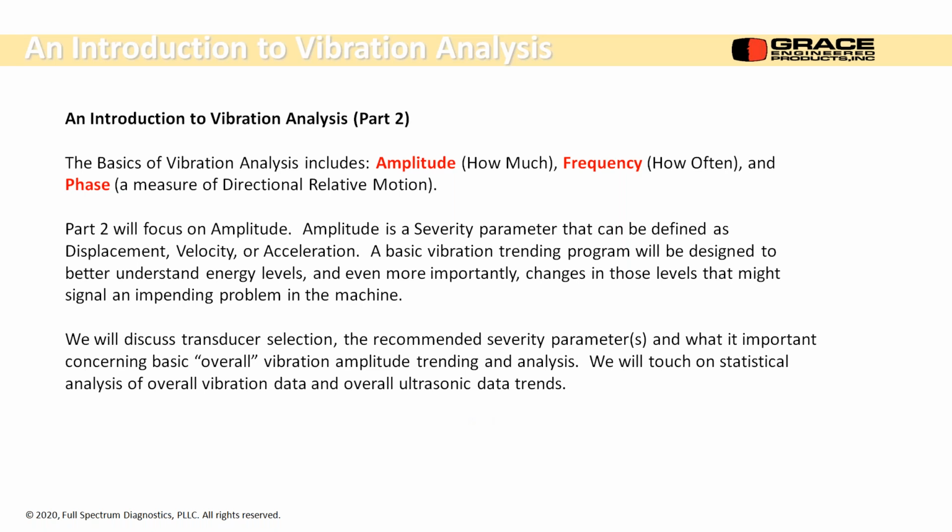I want to lead into ultrasonic data trends, and we're probably going to get into that next Tuesday. This is a secondary trending mechanism that the GRACE transducers have to offer. The first is you take an overall level and trend that. They also have spectrum and waveform capability on demand. One of the transducers in the triaxial is a higher frequency transducer, and we can filter it and adjust it so that we can see ultrasonic vibration.